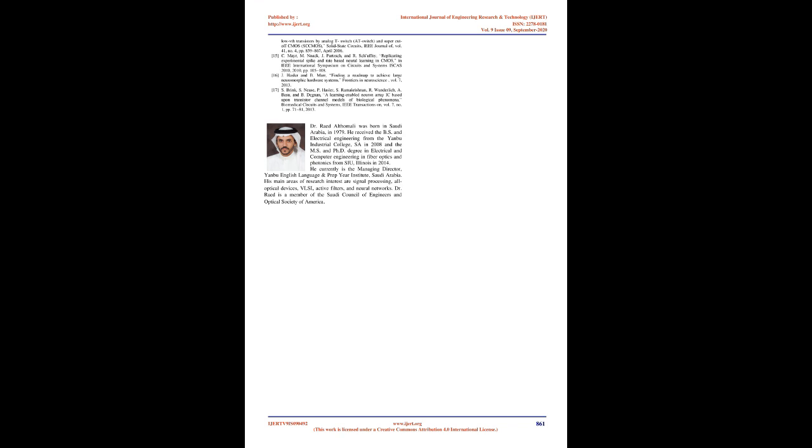There is a possibility of the appearance of an offset in the output due to less than ideal matching between devices in the aspect ratios, parasitic capacitances, and threshold voltages. Practically, I observe that the output of the proposed matching cell is not exactly zero. This is due to the non-perfectly matched device parameters and the parasitic capacitance coupled to the floating gate.